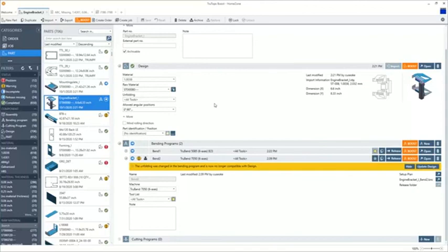We use a bend allowance. So even though the angle is the same and the material is the same, when I change that lower die, I changed my bend allowance. If I use a narrower die, I'm going to get a smaller radius, and I'm going to get a different stretch on that material. So the software is warning me that because I changed the lower tool, the flat no longer matches the bend program. So keep an eye on the dimensions here, the 6.6 by 8.33.